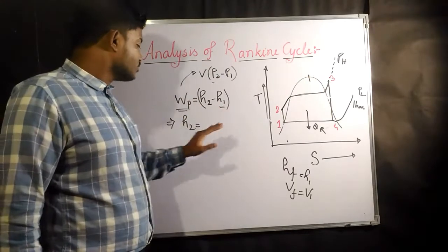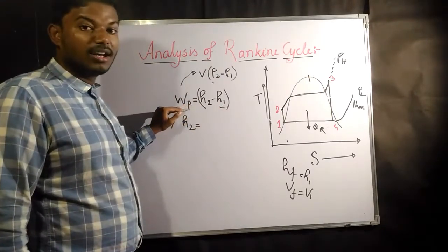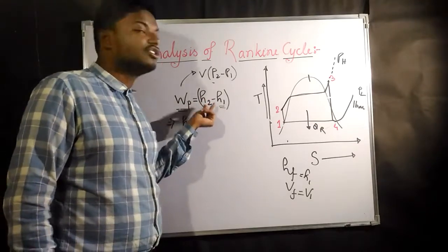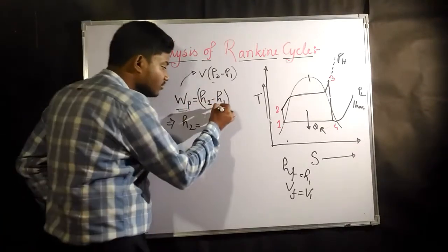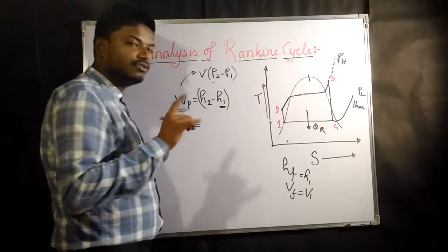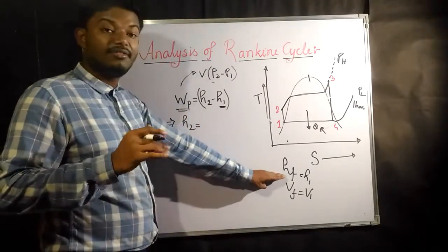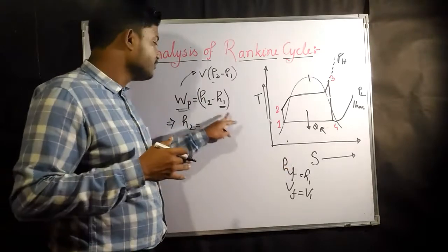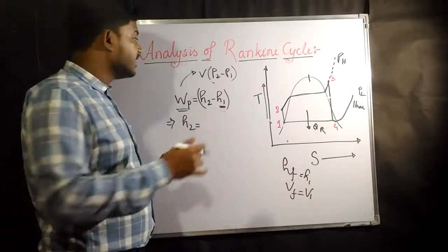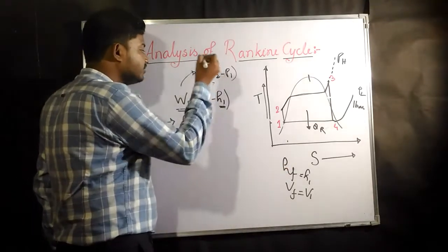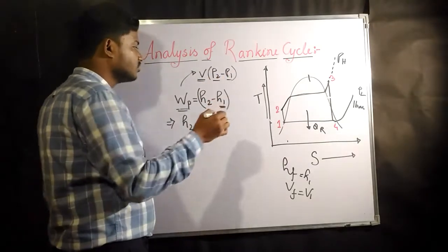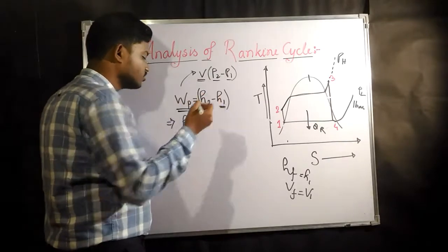Okay, so first of all, we did not find out the work done by pressure with the help of enthalpy difference. Why? Because finding out H2 was difficult. But finding out H1 was very easy, and if a steam table is given to us, we can easily find out the enthalpy at H1. Now in the steam table this thing is also given, and from the question these two things are also given. Now we can find WP also.